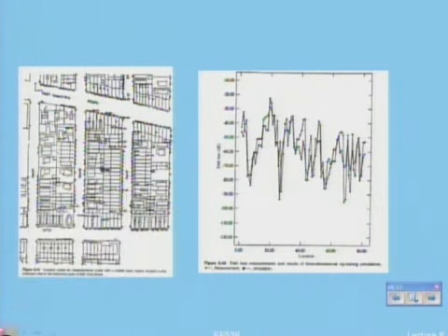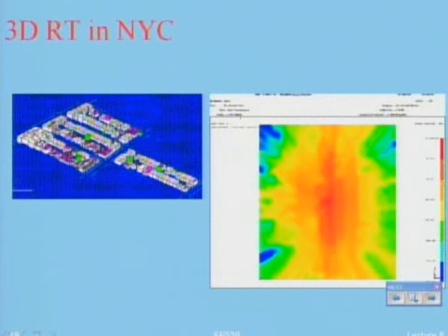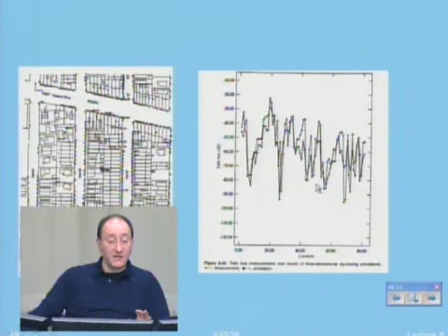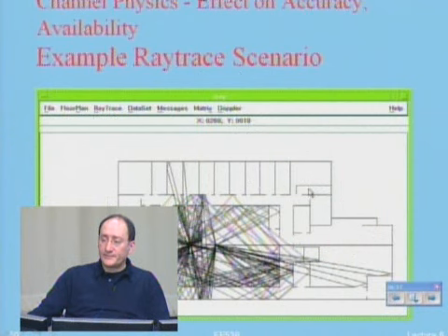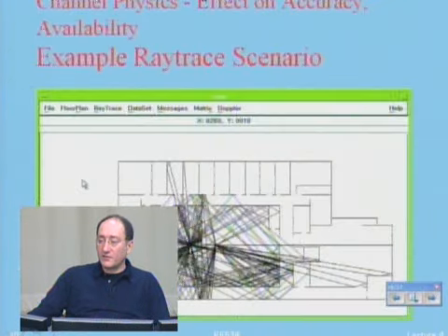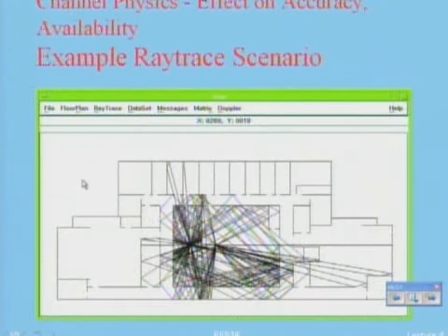These are, again, those blocks of buildings that we talked about, that we see here in 3D. And these are results of measurements, showing how close they are to ray tracing. Ray tracing provides very good results. But outdoors, it needs a lot of hand-picking of the locations where you diffract. So implementation is very difficult. For indoor, it's easy and good. Now, this is another ray tracing sample.